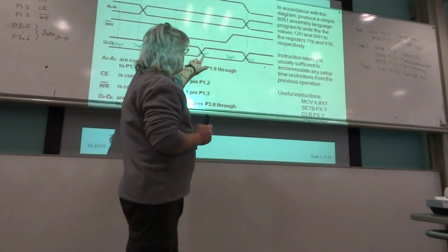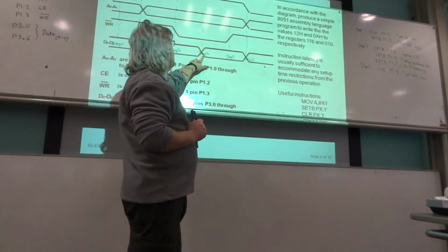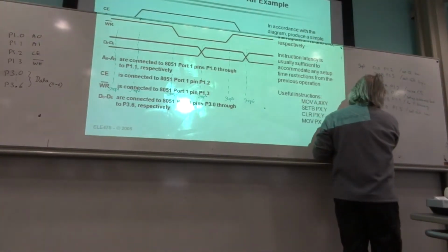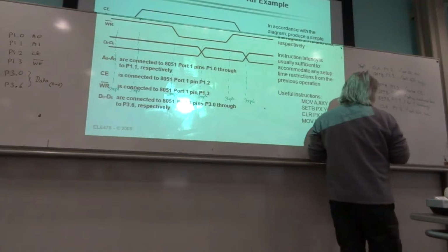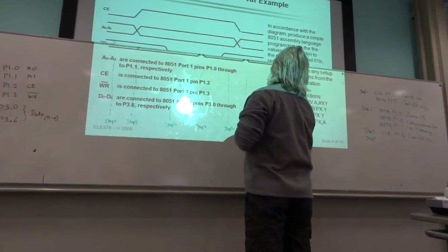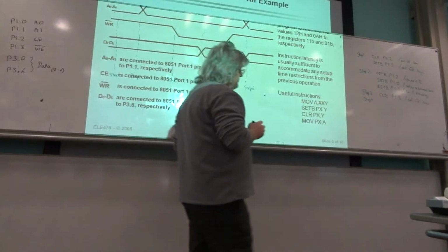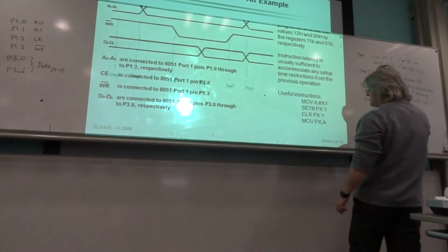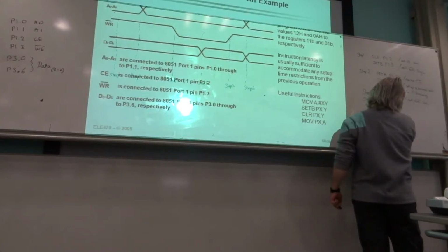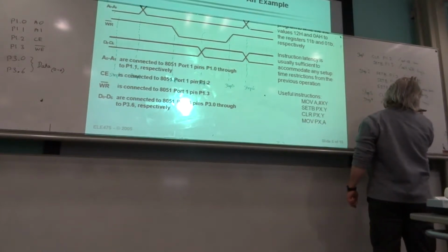Step 4 is where I'm actually setting up the data bus. Okay? And there's nothing else happening during that phase, so step 4, I've now got to write onto the data bus the value 12 hex. Now, I could, for example, do this, which is what they're kind of implying. So what I might do is move to the accumulator immediately 12 hex.